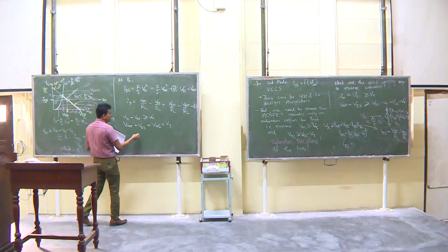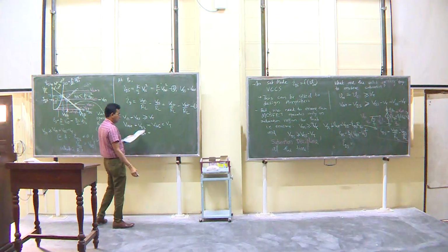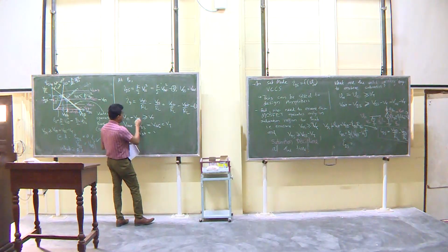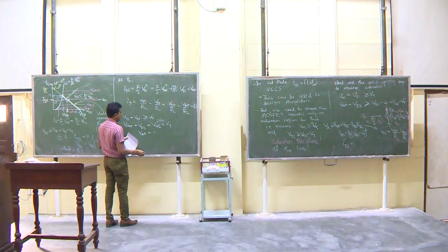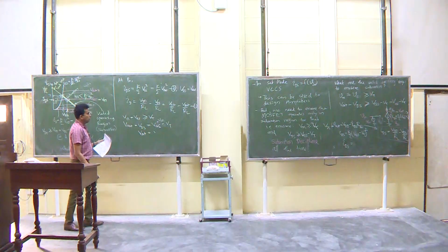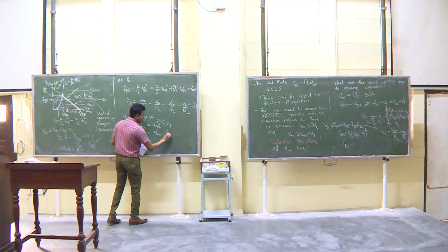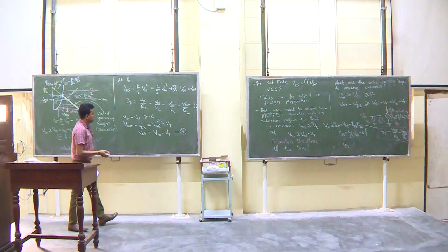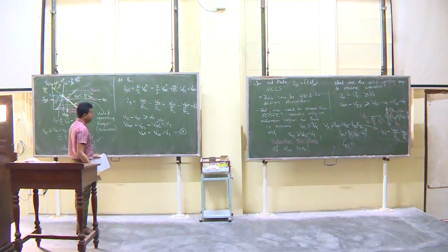So therefore, V out is equal to VGS minus VT. VGS is equal to V in. So this should be V in minus VT, let us call this 3. So V out is VDS, which is equal to VGS minus VT on this line. Okay.